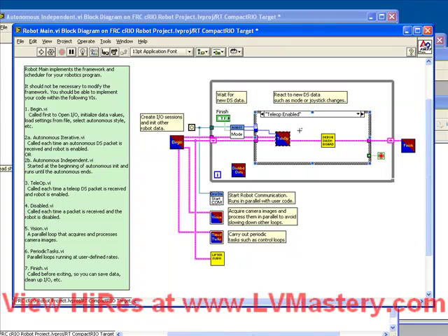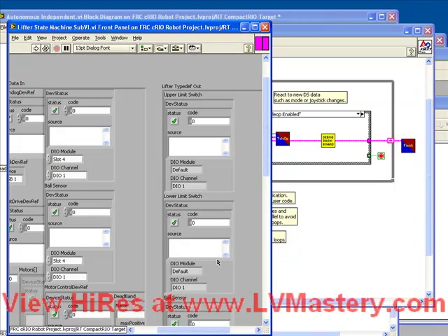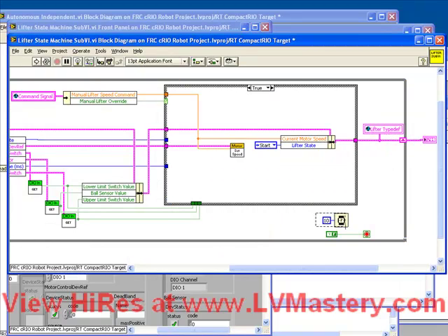So, to recap, we took the state machine which we created in a previous exercise to control a theoretical mechanical lifter out of the TeleOp VI and turned it into a sub-VI which runs at the root of the robot main. The reason for that was so that we could ensure that it had consistent timing and ran without a lot of other things slowing it down. Then we added a global variable which made it possible to export the values in its internal typedef so that they can be read by other VIs and by our debugging dashboard.